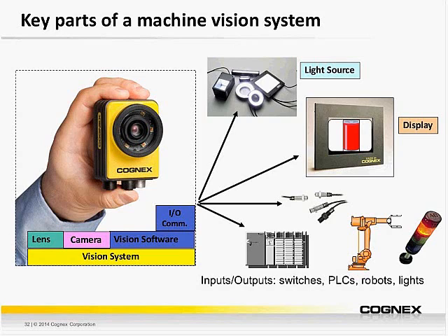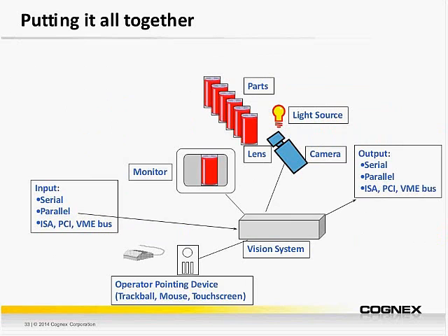Generally, today's machine vision systems are divided into 4 platforms or types. There's PC-based machine vision systems, vision controllers for multi-camera applications, vision sensors, and smart camera vision systems, such as the yellow camera on this slide, which is actually a fully integrated machine vision system that includes lighting, autofocus optics, the camera sensor, processor, and communication. And choosing the right machine vision platform generally depends on the requirements of your application, with the key differences being the development environment, capability, architecture, and cost.